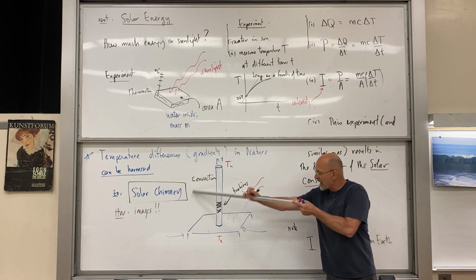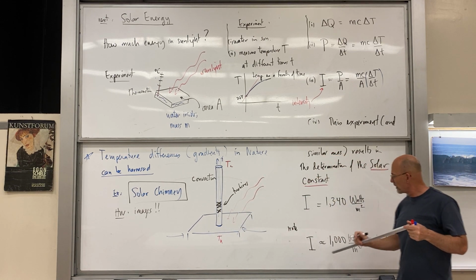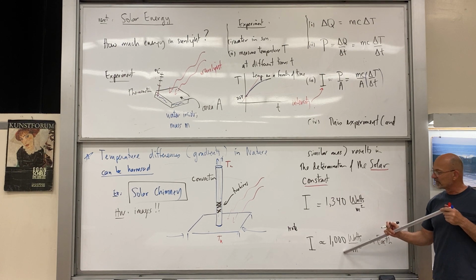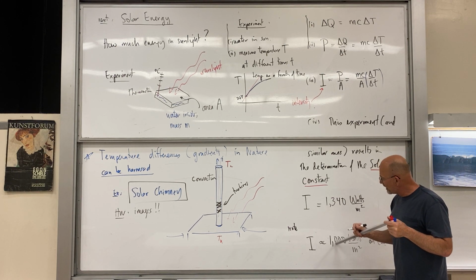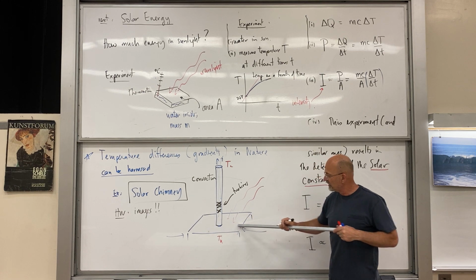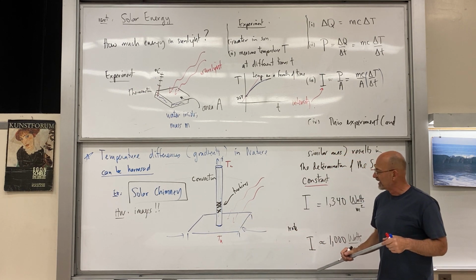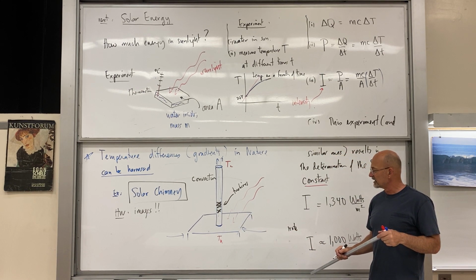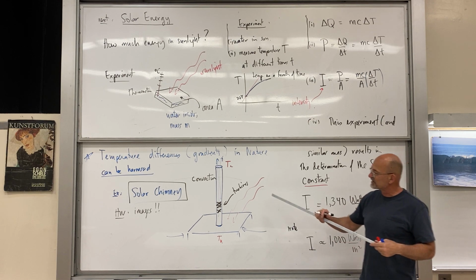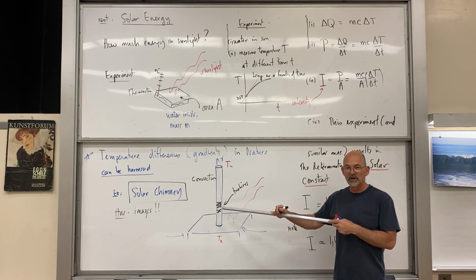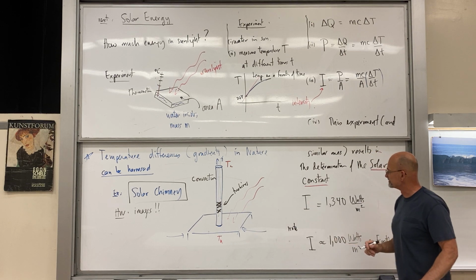For example, this contraption here, once you know this number, and let's take the 1,000, so you take this 1,000 for every square meter in the canopy, and then you multiply by that very small efficiency, and that'll give you the maximum possible output of such a device.